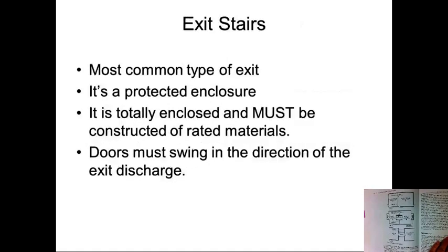Let's talk about exit stairs. It's the most common type of exit, especially when you have multiple floors. It is a protected enclosure. It is totally enclosed and must be constructed of rated materials, and doors must swing in the direction of the exit discharge. So you can see the example here, how it swings into the stairwell.